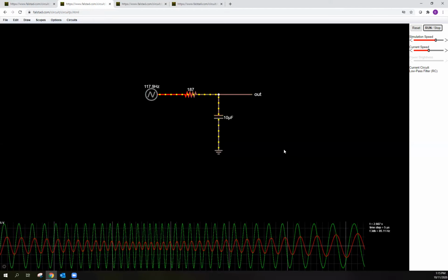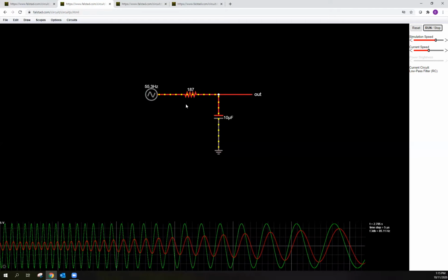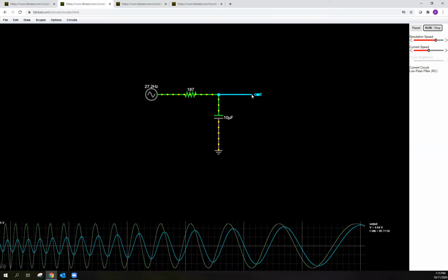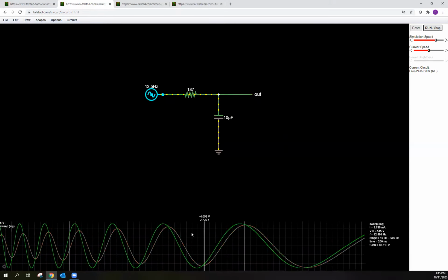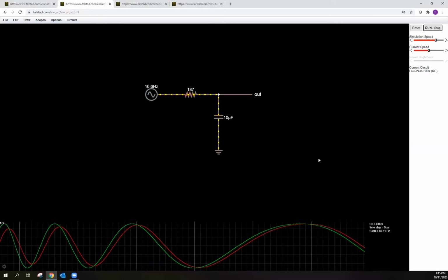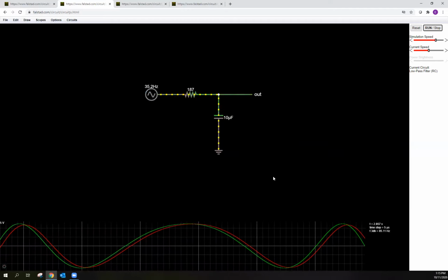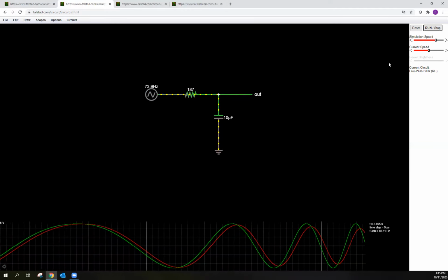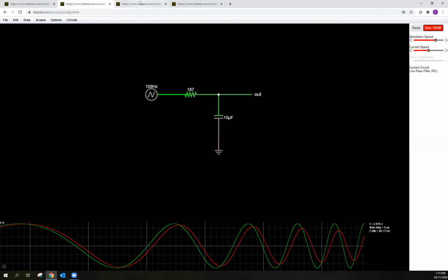We'll talk about the phase a little bit later. You can see at high frequencies, just a little foreshadowing, the phase of the output starts lagging the phase of the input, right? The red line is behind the green line in time, it's lagging, okay? And we'll see that. Okay, let's look at a high pass filter.